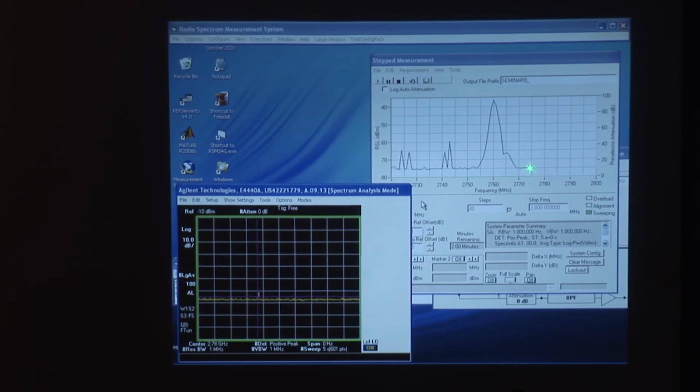And I emphasize that if this radar were doing some complex frequency hopping, if it were doing complex beam scanning, it wouldn't make any difference to this measurement algorithm. We would get it just as well, just as long as we wait long enough for every single one of these measurement points. For a given radar, this could be anywhere from 1 or 2 seconds to as much as, for some weather radars, up to 1 minute per point. For most radars, it falls between 5 to 10 seconds per point.